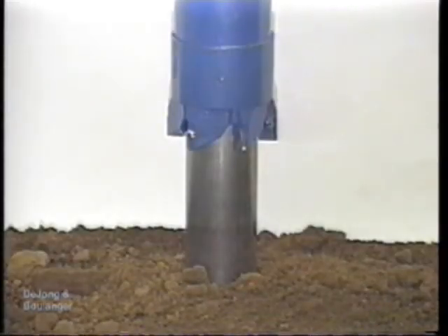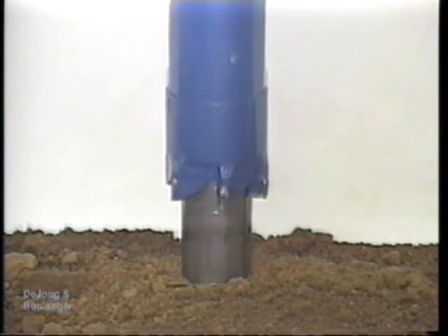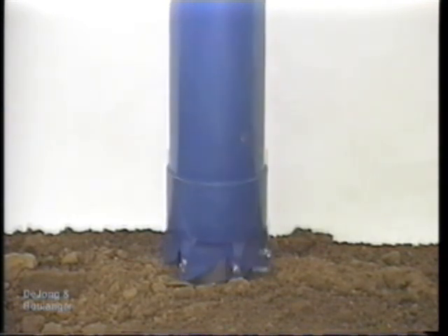If the soil is soft, the spring at the head of the tube keeps the cutting edge of the tube below the cutter barrel, and the tube is pushed into the soil just like ordinary tube sampling. If the soil is hard, the spring is compressed until the cutting edge of the tube is forced above the bottom of the cutter barrel. As the barrel rotates, it cuts an annular ring, leaving a cylinder of soil over which the sample tube slides. The tube thus protects the sample against erosion by the circulating fluid. In this manner, the pitcher sampler adapts itself to the stiffness of the soil.